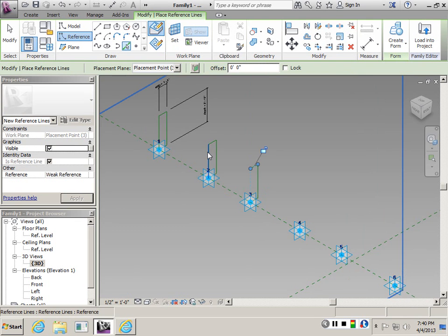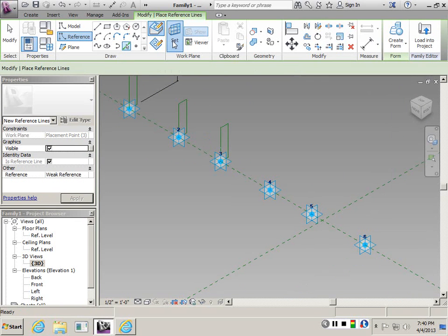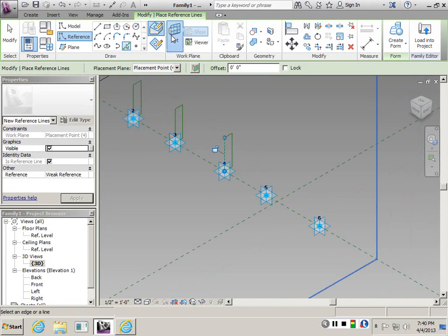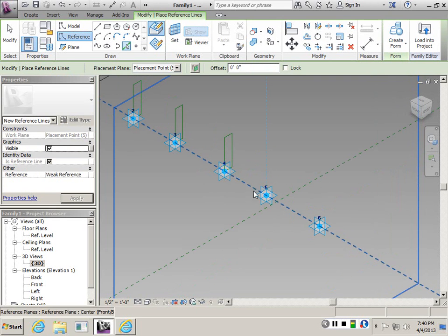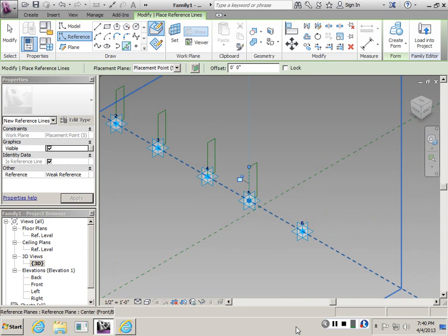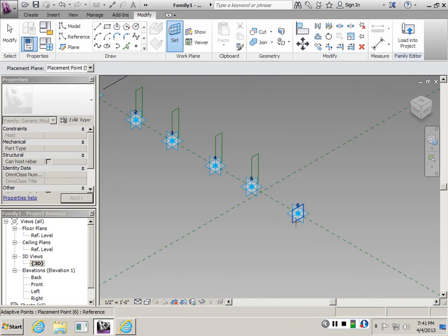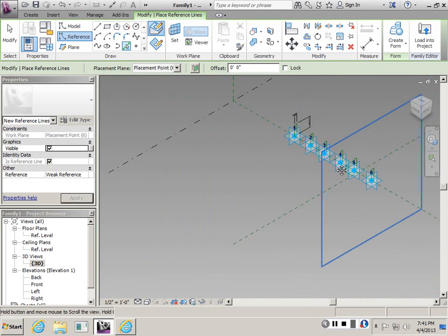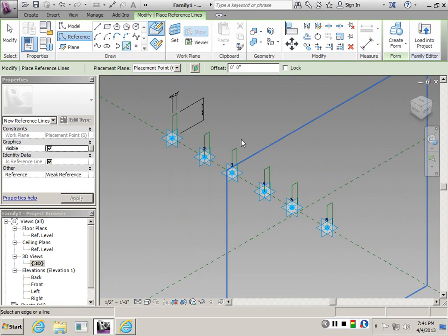so that I have a profile on all the adaptive points. So I first set up the new work plane, and then using the pick line tool, I create the same profile here, and I'm going to do the same thing here. Pick lines again. So it's pretty fast. Let's keep doing this. So I do the final one. Okay, so the profiles are there.